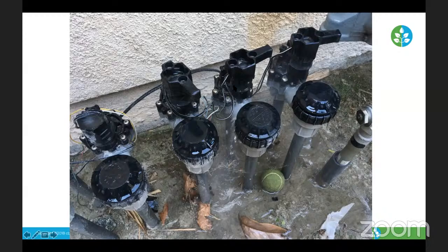Once the valve is not operating, where it's in a resting state, it does not leak. So that could be a little bit of an issue if you don't do an irrigation check. You might not see this leak. Over time, you can see that this is a really wet area. This was pretty sandy, so the water wouldn't puddle as much. But something that does happen.